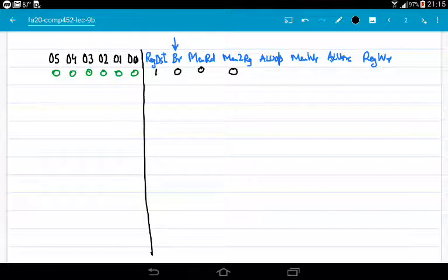What would be ALU op? You know, for R type instructions, ALU op 1 is 1 and ALU op 0 is do not care. So 1 and do not care. Okay, what will be mem write? Mem write will be 0. We do not want to write any memory.